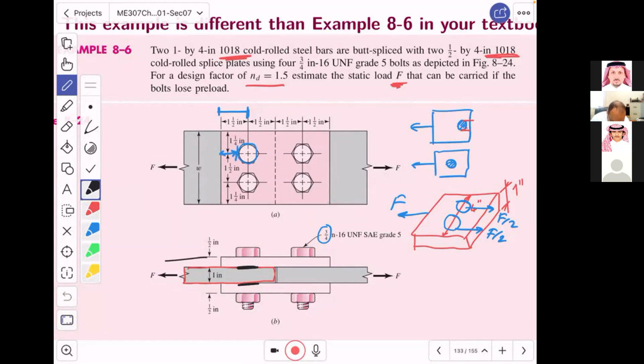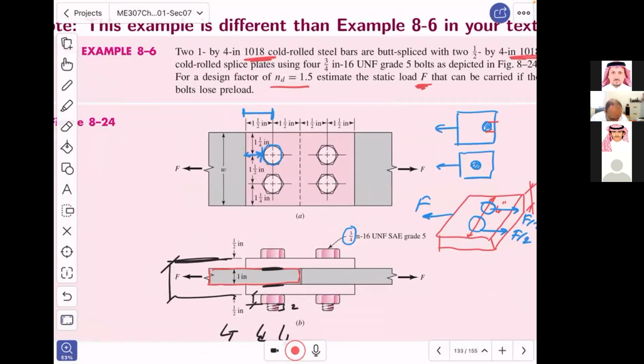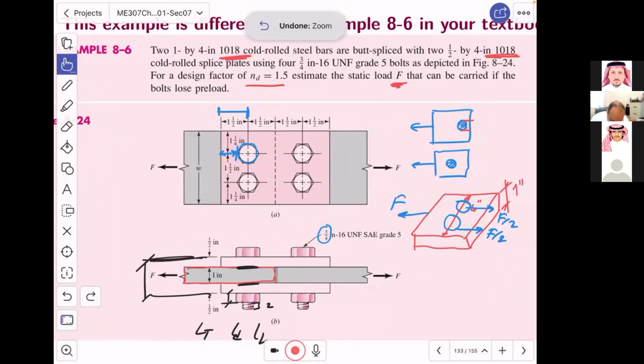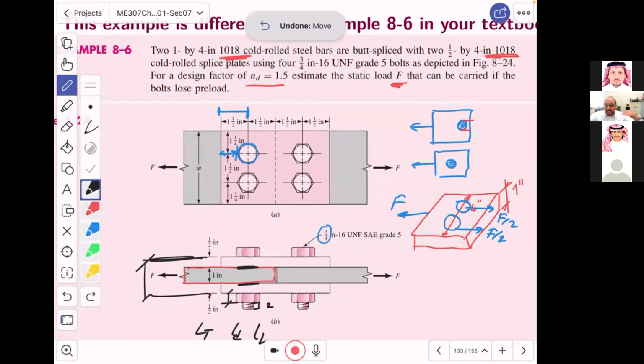You will go find the length of the grip, all of it, and then add to it the height of the nut, and add to it at least 2 threads, and then find LT, and then find LD, and then find the small lt. And you will know exactly what this is. Is this area in the thread or not? Now, what are the consequences?